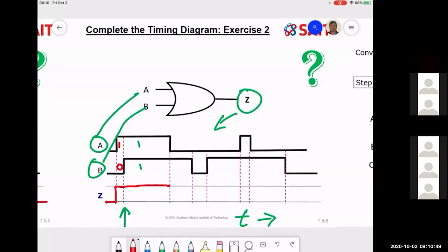Through to the next transition line. What would the output be after this next transition line? A 0. No, this is an OR gate. I have a 0 or a 1. Oh, okay. Well, that would be 1. A 1. Next line: 0 or 1. 1. I've got a 0 or a 0. Oh, okay. Well, then that would be 0.